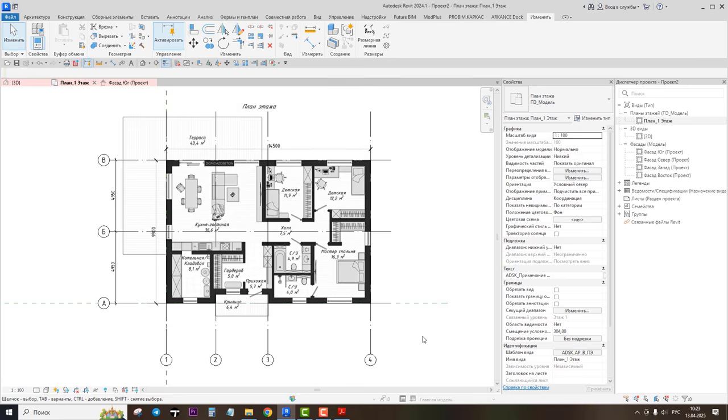So first, just limit your house dimensions, width and length. Make just a 4-line grid, for example, 2 vertical and 2 horizontal ones. And all the rest you can make anytime you want, actually. Okay, before we start designing our walls, we need to make one more building level. The point is that walls in Revit depend on one level and another.